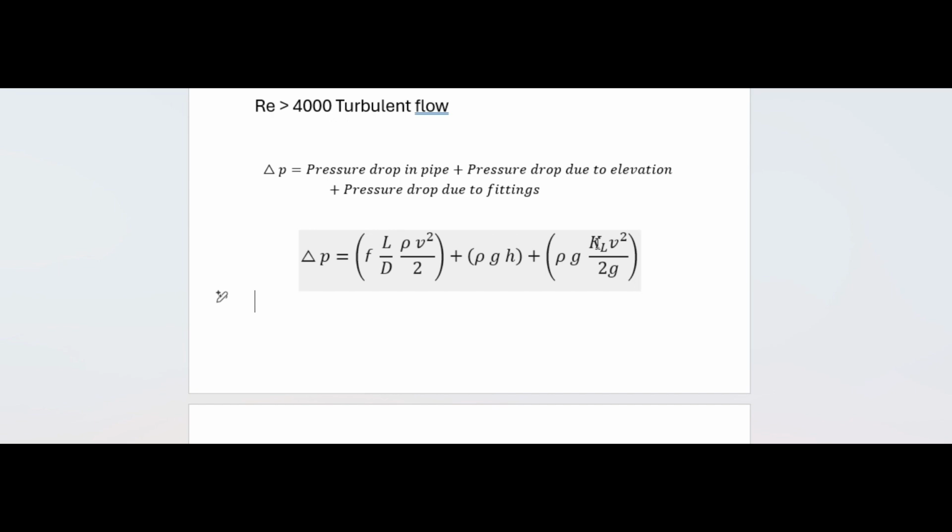The trick is that it depends on the length of your pipe. You could use an equivalent length factor, and in that case you actually don't need the fitting coefficients. If your pipe is from 50 feet to 150 feet, you could use a factor, and that factor is different for each diameter.